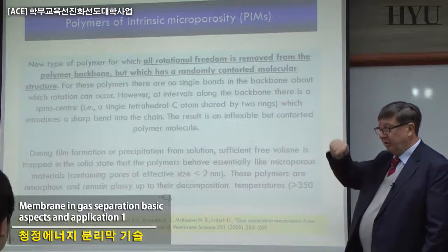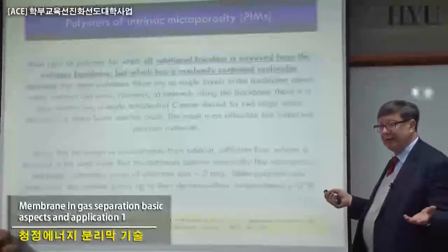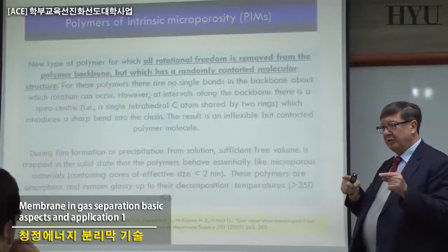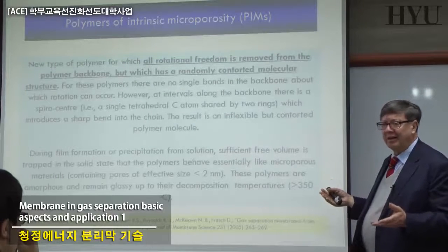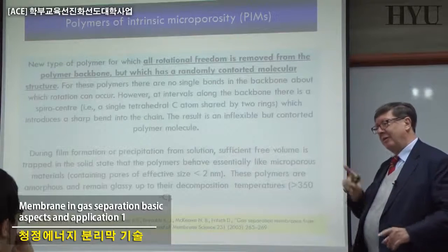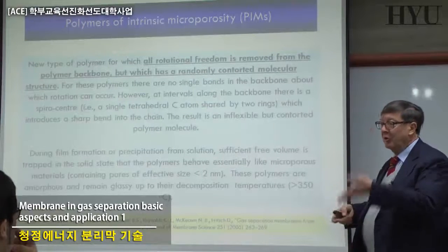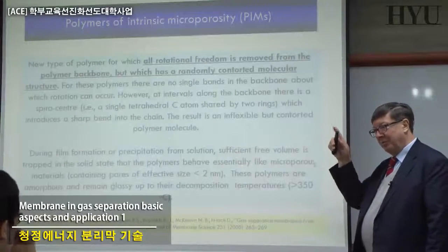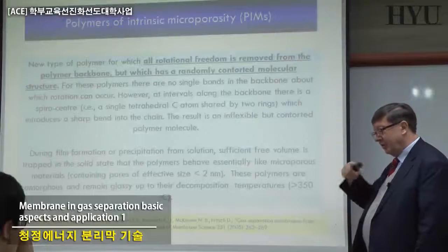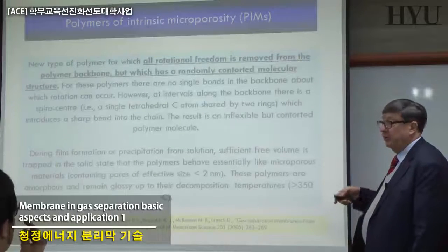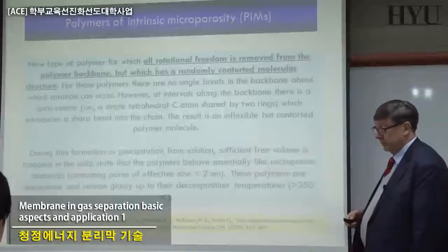And in cellulose acetate you can change significantly. Membranes produced at 20, 30 degrees centigrade have relatively very low selectivity. If you treat these membranes at 90 degrees, they were called CA90. People say, what does CA90 mean? It's not that something is changing in the polymer. It's the temperature at which the membranes have been treated after preparation to increase the selectivity to 90%. You have to go back 30 years, 40 years, and you can find in the literature this typical plot for CA. Something very similar, different temperature, different polymer, 450, but you can have the same kind of situation.